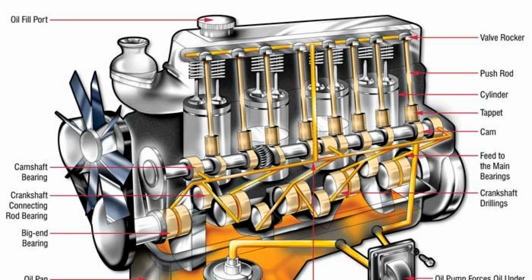The first ones are installed in such a place that a powerful flow of oncoming air runs onto the radiator. The second ones use coolant circulating through the system. Ensuring the required pressure is not an easy task, as the engine usually runs irregularly, either with an increase or a sharp drop in RPM. When the vehicle accelerates, the pressure in the lubrication system can build up above a critical level, which can have irreversible consequences for the power unit.